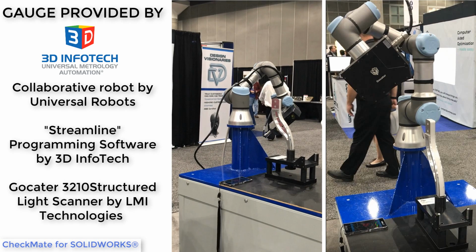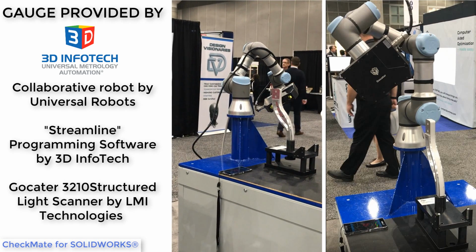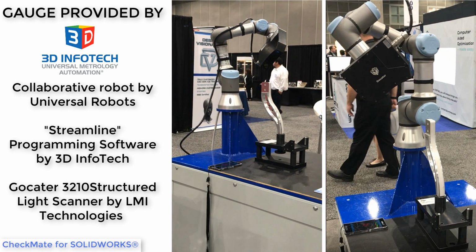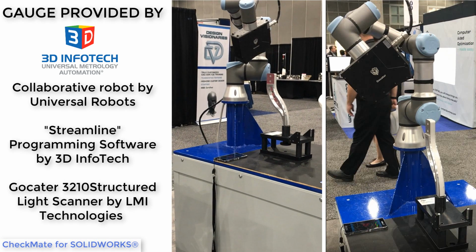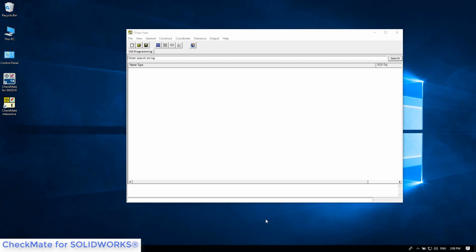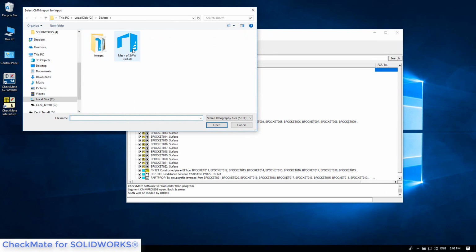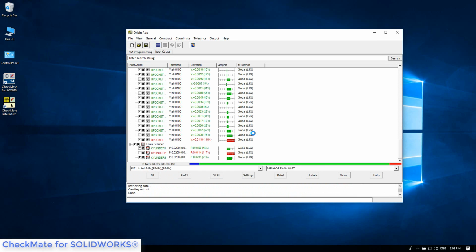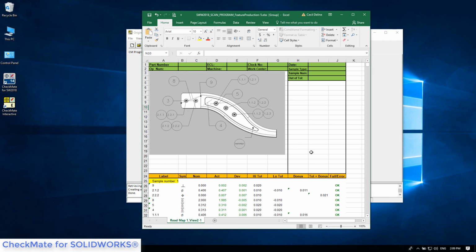The 3D scanner begins scanning the production parts, creating the STL digital part for each. As soon as the part is finished being scanned, the STL digital part is automatically evaluated. Whether simple deviations or complex GD&T patterns performed by SawFit, the authored CheckMate soft gauge performs its evaluation. We finish with an inspection report being automatically generated.